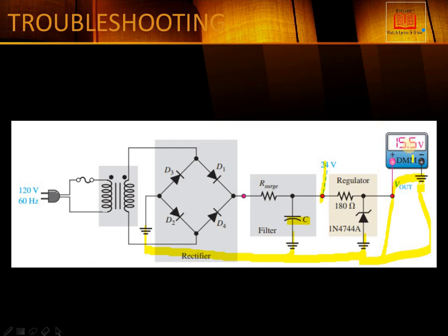Okay, here 15.5 volts, definitely some voltage shown exceeding 15 volts, because these are rated a little bit higher. When load is connected, the current will definitely be divided into the load and the Zener diode. When the current is divided, some goes towards the Zener diode and some part goes to the load, then automatically this voltage will decrease.